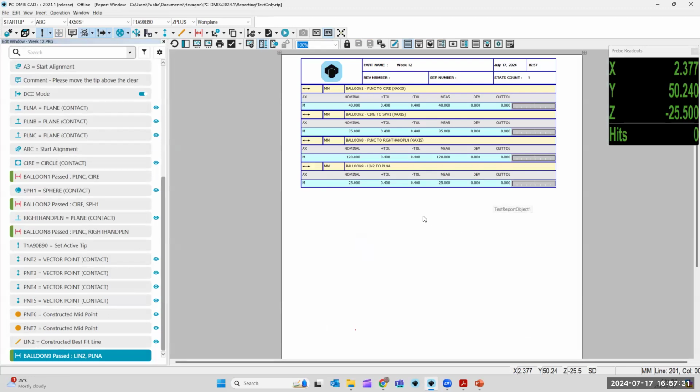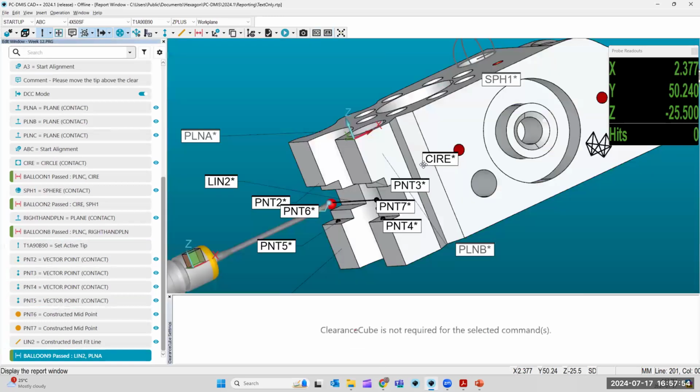Technically all you have to do when you're running and executing it is 4 points are taken, and then it's going to build everything else and tolerance it. That'll all happen instantaneously in the software. But it physically has to make those 4-point contacts because they're measured points. So it has to physically find where they're located. So that's dimensioning, and that is constructed features.